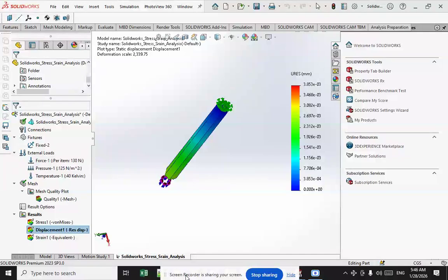The fundamental problem. The fundamental problem in stress analysis is to determine the distribution of internal stresses throughout the system given the external forces that are acting on it. In principle, that means determining implicitly or explicitly the Cauchy stress tensor at every point.